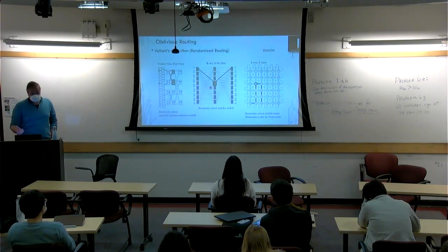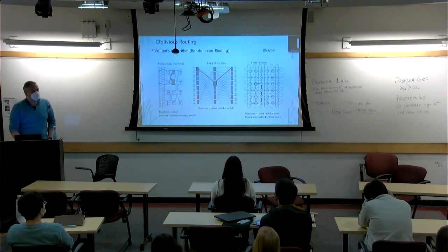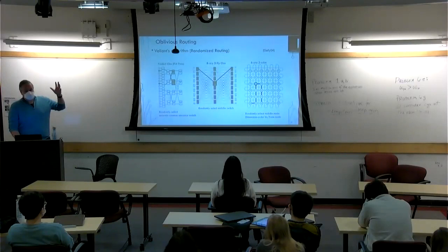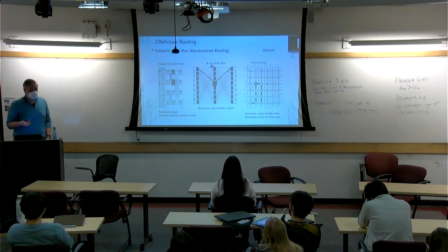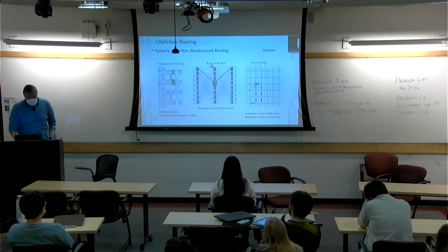For the oblivious routing, as I mentioned, I already kind of mentioned this clos example. Once you're in this switch 1, you need to decide which middle switch you're picking, because any of them can take you to the group you want. So you flip an 8-sided coin, and you get a number, and you go to that one. That way, you're randomizing the traffic across all of these switches, so you're trying to avoid congestion. It's a little price to pay to be able to leverage that degree of freedom that you have in the system compared to butterfly.